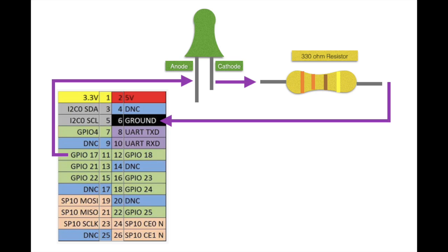And you'll notice that we've got a variety of different green GPIO pins labelled here. All of these are not assigned for other jobs and are literally for any inputs and outputs that we might require from the pins. Very irritatingly, strangely arranged in different places, and the ones that we'll be using for this project are 11, 13 and 15. So I'm going to start off by just using 11 as shown here, and I'll show you how